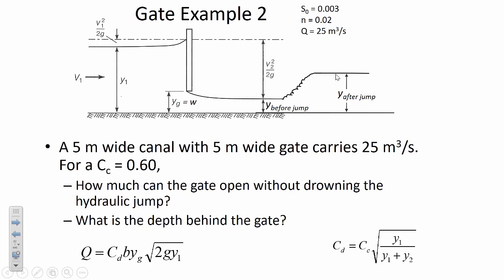And then finally, in phase 3, you're going to find the Y before the jump with the Belanger momentum equation for the hydraulic jump.